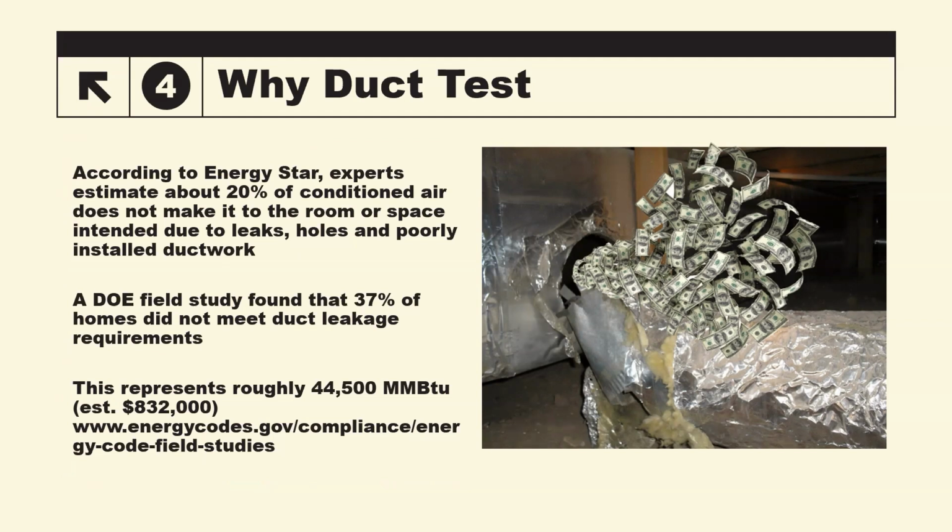And we've talked about that extensively on previous webinars about how crushed ductwork or kinks or sharp bends can reduce efficiency, comfort, all of the above. So they've estimated about 20% don't make it. If you're looking at a 1600 CFM, 4-ton system, then 20% of that's not making it to where it needs to be. And that leads to pressure imbalances that we'll talk about in the next slide.